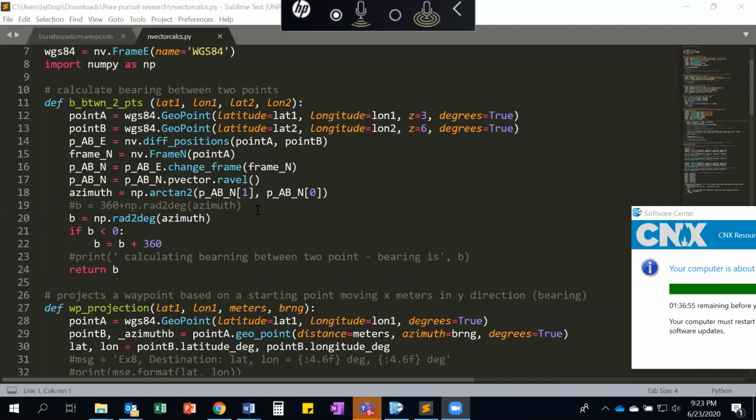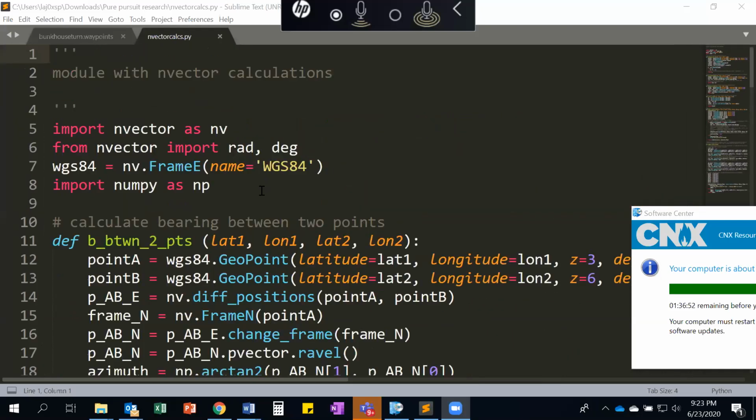I was going to say earlier, when we were talking about position-based navigation and path-based navigation, alluding to the difference there, and I think Matt can speak to this, but for the most part at ASI, we're dealing with path-based navigation. You plan a path and the tractor tries to stay on it, calculating off-path error, and also staying on the heading of the path. That was how we did it.